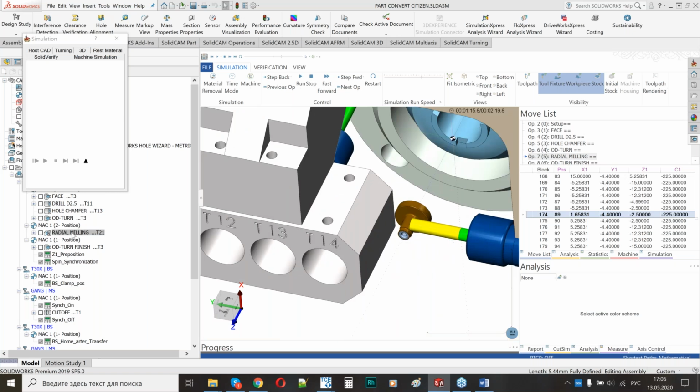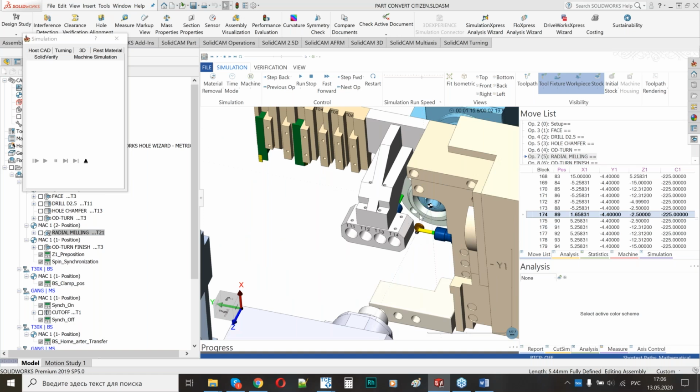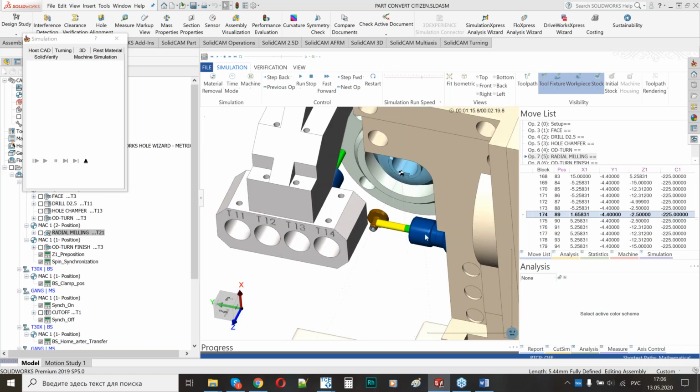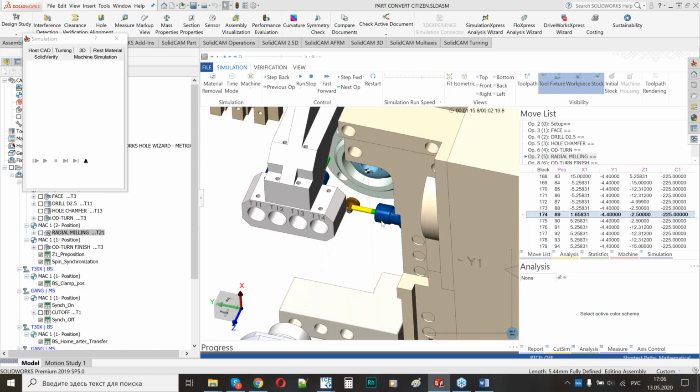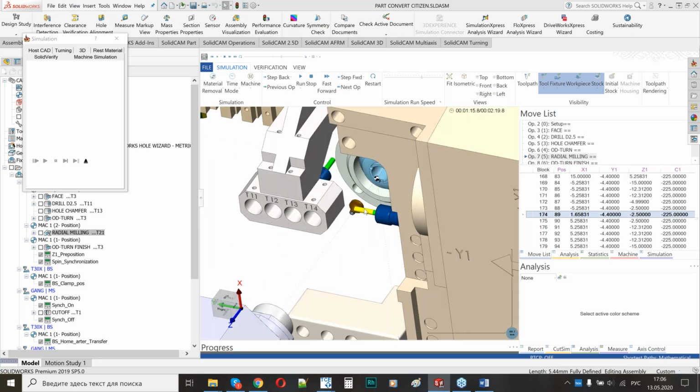The original position of the axis of the operation was okay for this tool. If it were inclined, for example, I would get a message from the system that it's impossible to add a 5-axis operation here because this machine doesn't have an additional rotation axis. But for this operation, it is okay, and I don't need to add anything additional here.